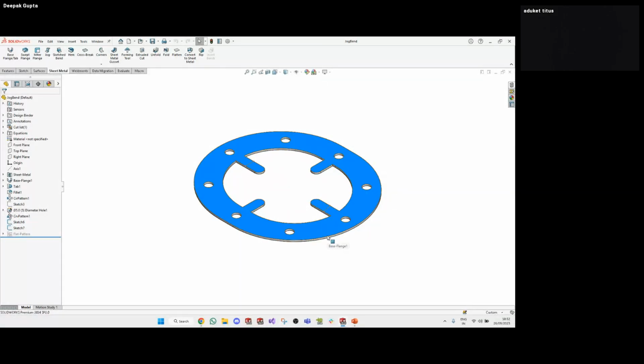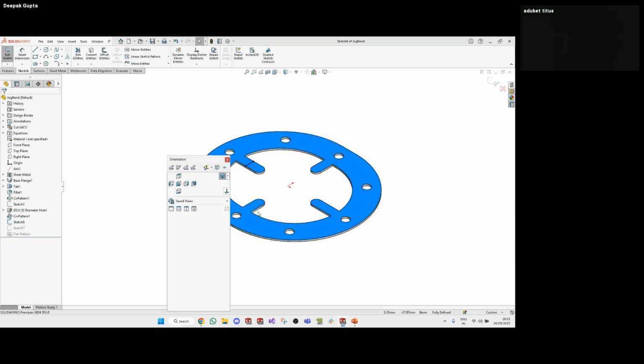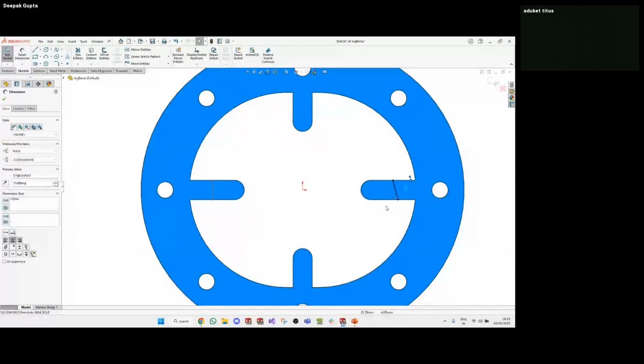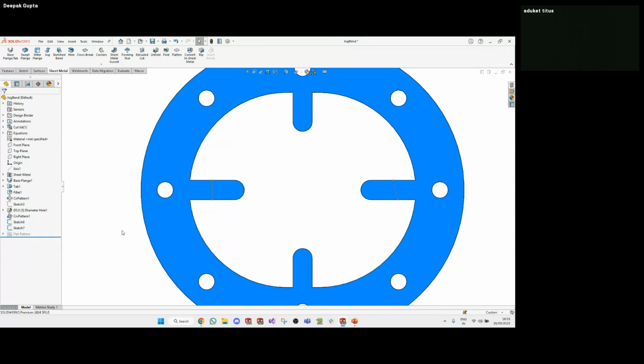In this example, I have a cover of a part or an automotive component, and I have created two different sketches. So let me show you. The first sketch is perpendicular to this face because I want the bend to be perpendicular, and the second line I have at about 75 degrees. So let's look at the first one. You can pre-select the sketch or select it later on. I prefer to select it first, and then I click on the jog bend.